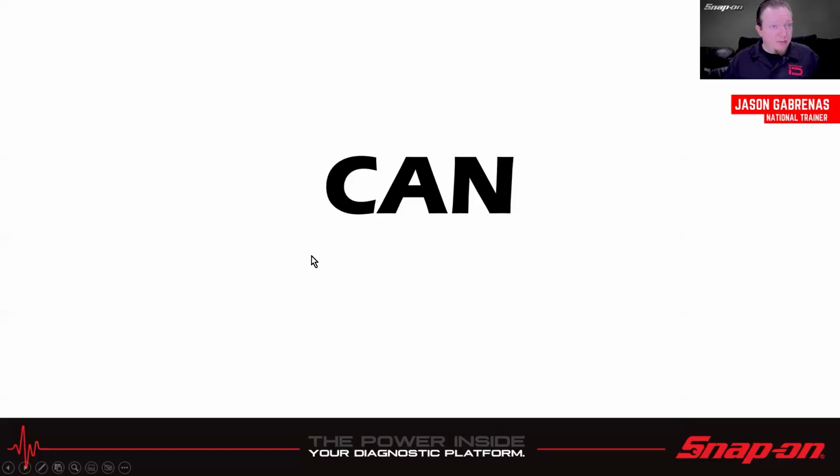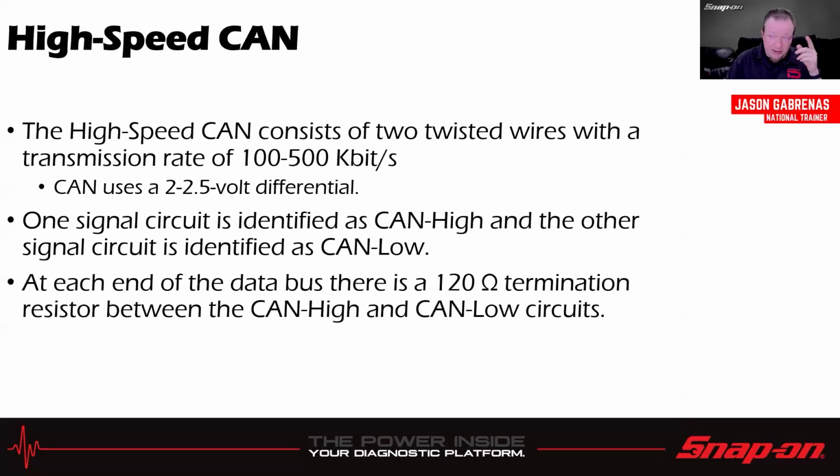And then we get the CAN. CAN is probably the most widespread network topology or network communication protocol. Probably the most common network communication protocol around now. It's been around for quite some time. So there's different speeds. There's low speed, high speed, mid speed. High speed CAN consists of two twisted wires with a transmission rate of 100 to 500 kilobits per second. And it uses a between 2 and 2.5 volt differential. There's a little bit of a range that's allowed in the spec.